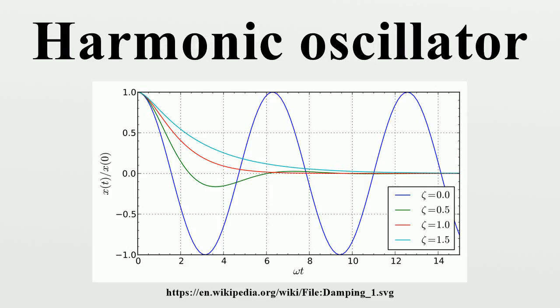Spring mass system. When a spring is stretched or compressed by a mass, the spring develops a restoring force. Hooke's law gives the relationship of the force exerted by the spring when the spring is compressed or stretched a certain length, where F is the force, k is the spring constant, and x is the displacement of the mass with respect to the equilibrium position.